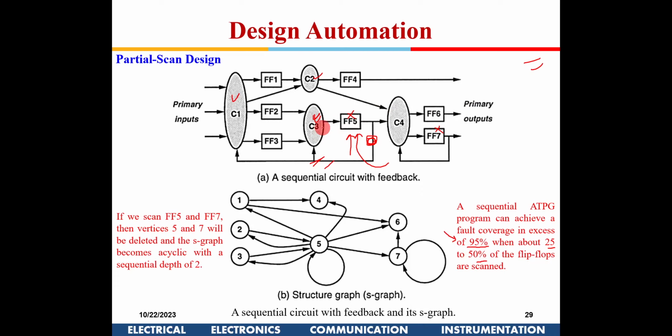So in the built-in test you will see that a large number of test vectors is serially given, and all the outputs are combined into a signature, and you do a signature analysis. All those things will be incorporated in the built-in test itself, right? So most chips will come with a built-in test. Once we are initializing a circuit, the built-in test will run, and if there is a fault, because with aging also faults can happen, right? So it is not a one-time test like what we did till now, post fabrication.